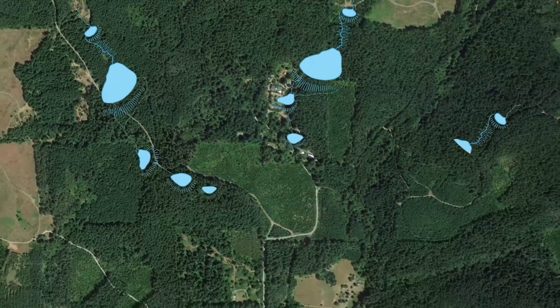And so we evaluate the rate of percolation to get another read on the soil's ability to hold water. We can also combine lab analysis with the Emerson test and Atterberg limits to look at the way that clay reacts with water, expansion and contraction, plasticity. There are a lot of things that we can look to do this soil suitability analysis.